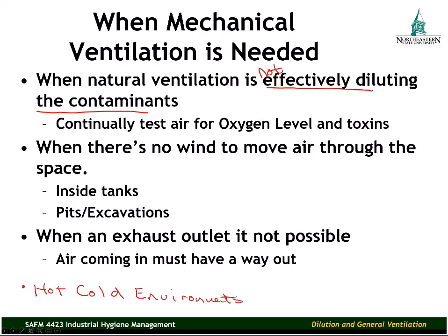I do address this later in our presentation and our discussion, but if you're in an area where air temperatures are 95 degrees plus, and that's what you have available as ventilation air through your workspace, that might not be suitable. You may run into other problems when you're bringing in 95, 100 degree air into your workspace. Natural ventilation is not going to work perhaps in those situations.